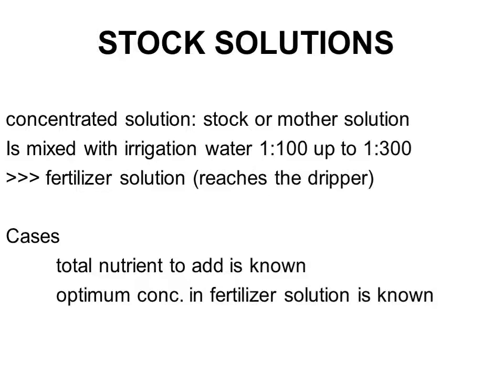The ratio between the concentration in the stock solution and the concentration in the irrigation water, this concentration factor, can go from, let's say, 1 to 100 to 1 to 300 typically. It could be even much higher depending on conditions, but it is safe not to go too high, because we can start to have problems of precipitates if this ratio is too high.